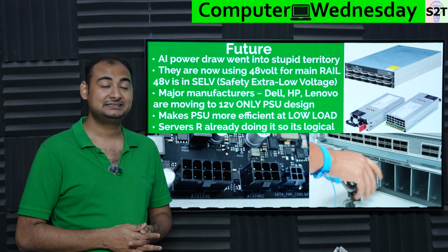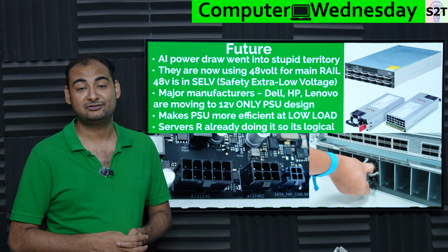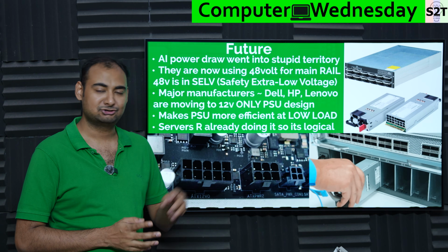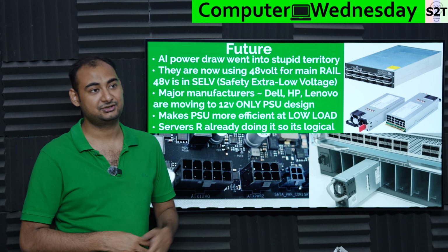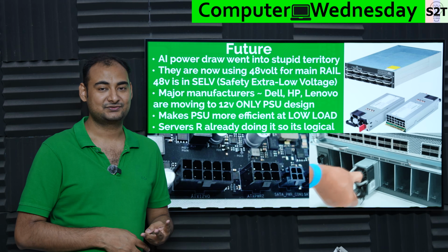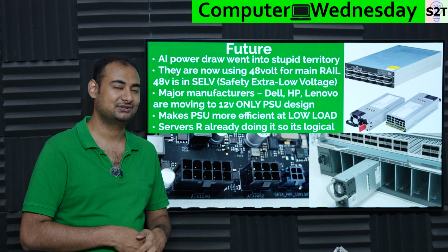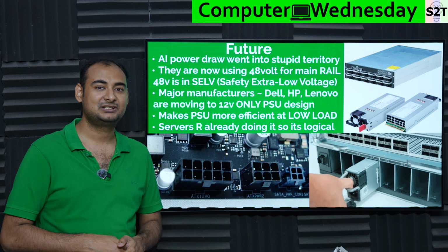How high up? Silicon MOSFETs will not do. You have to use silicon carbide or gallium nitride. And not to mention, at very high frequency, ringing becomes an issue, and inductance becomes an issue. You can't even use 3-pin MOSFETs, you have to use Kelvin connection MOSFETs so you can switch reliably. So all of that becomes a hassle.